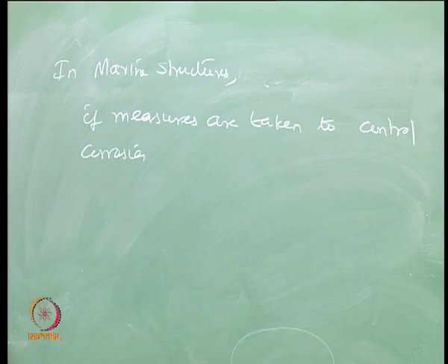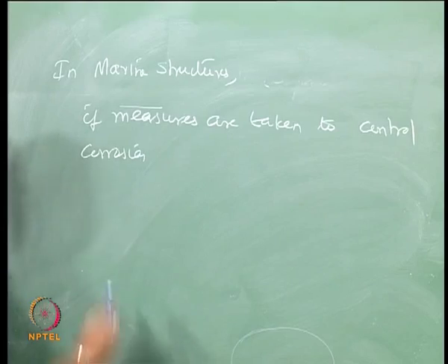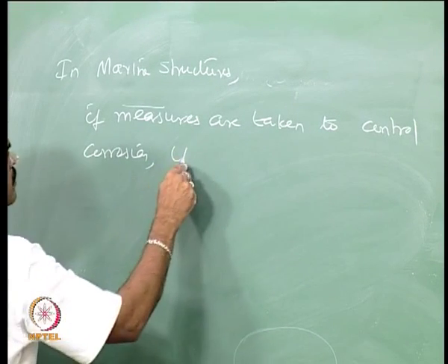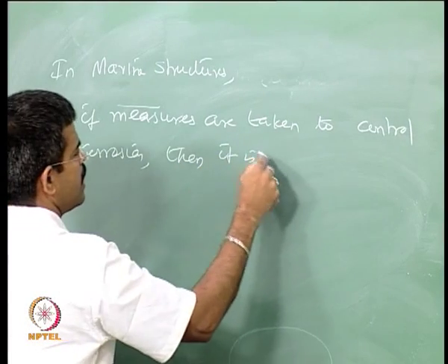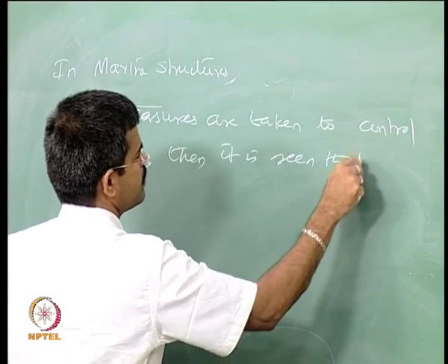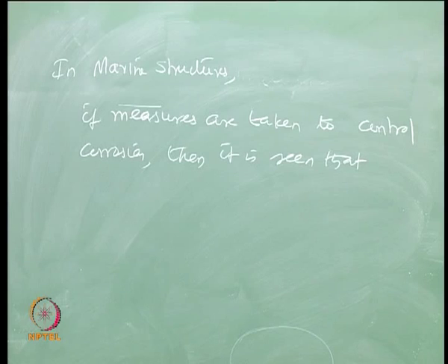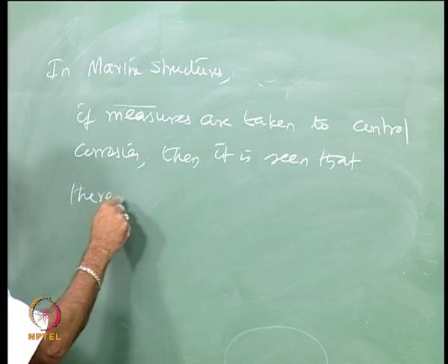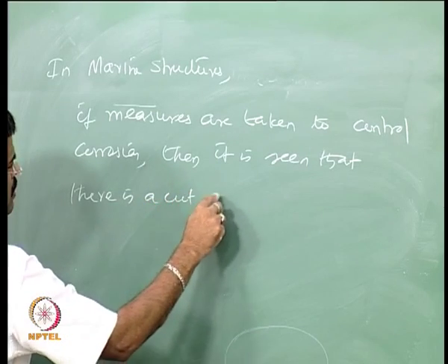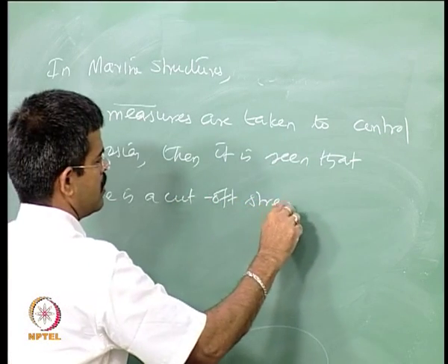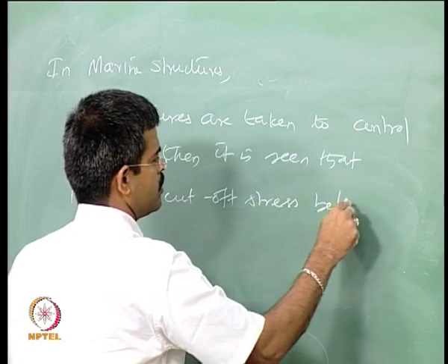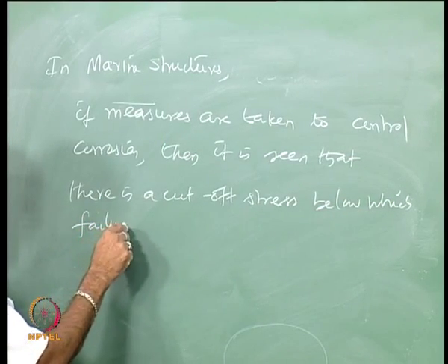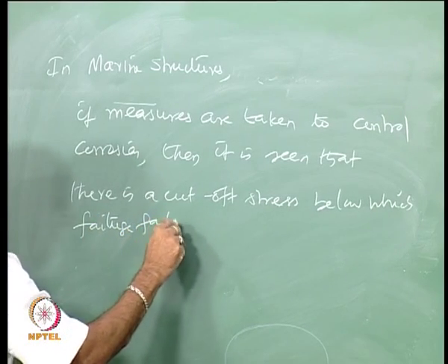If I adopt all those measures to control corrosion in a marine structure, then it is seen that there is a cut-off stress below which fatigue failure will not occur.